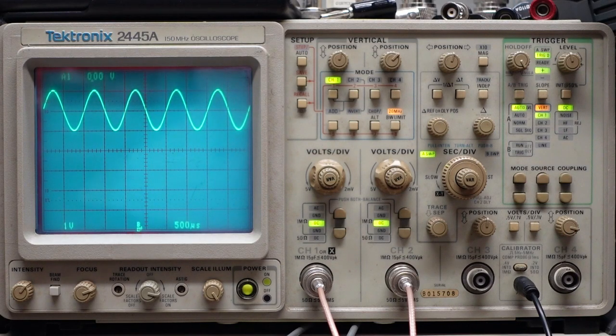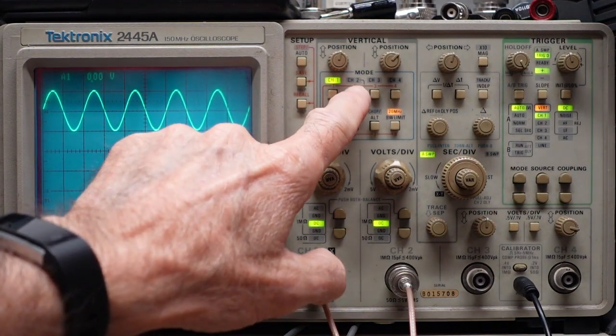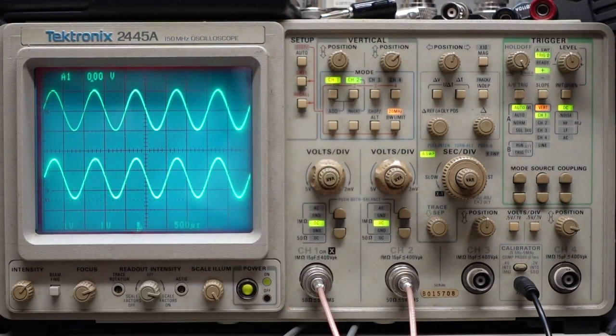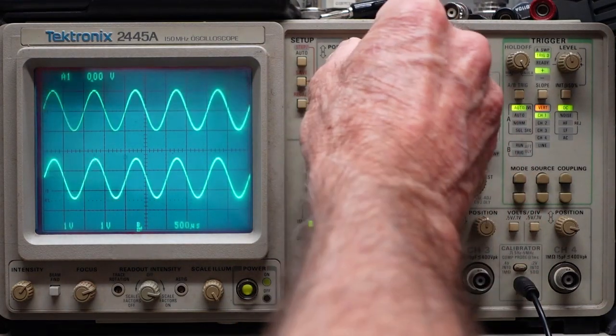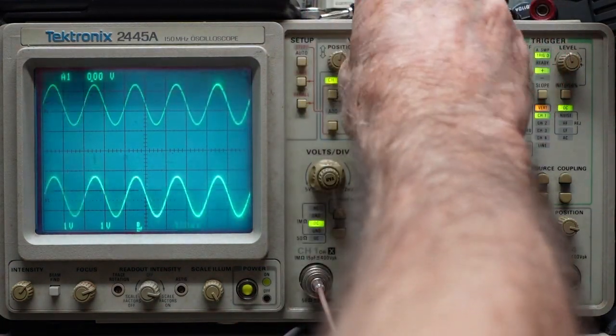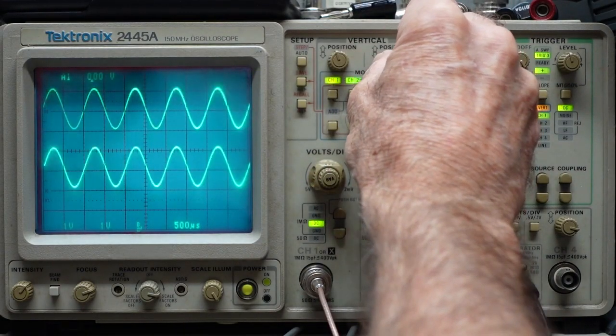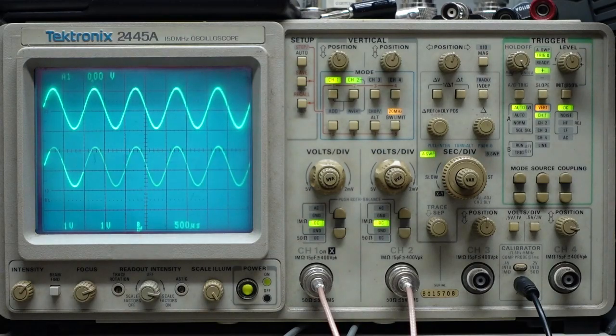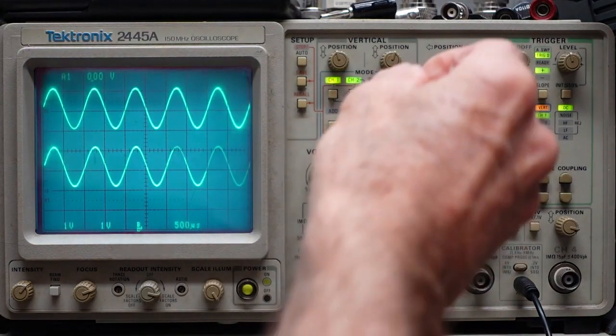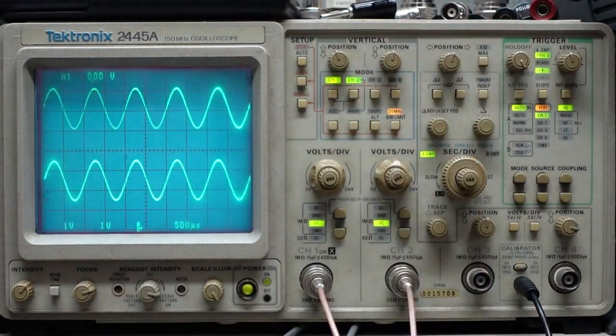So the top trace would be left, and we wanted to take a look at 2 channels at once. Now, I'm feeding the same signal into both channels with a simple Y connector. On this scope, I simply select channel 1 and then turn on channel 2, and I have 2 independent channels or traces. Okay, so I can put the one on top of the other, and it's just very handy. This way I can look at both channels at once and see if I have a problem.